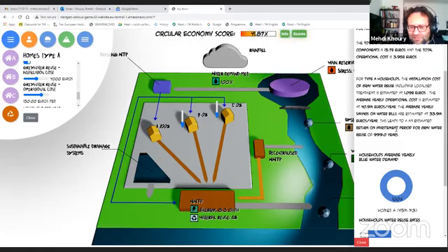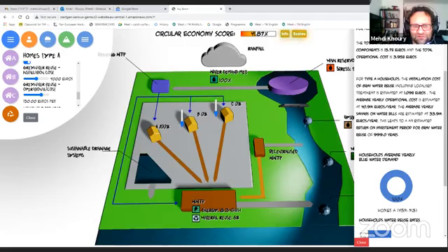You're going to get your money back in 1,000 years with the present cost of using gray water reuse. Well, the problem is the operational cost is too high. If you use a filter, which is just a household-based filter, then it's just going to cost you too much. So gray water reuse might work financially if you were to reduce the operational cost, if you were to group the filtering by neighborhood, for example, centralize it.